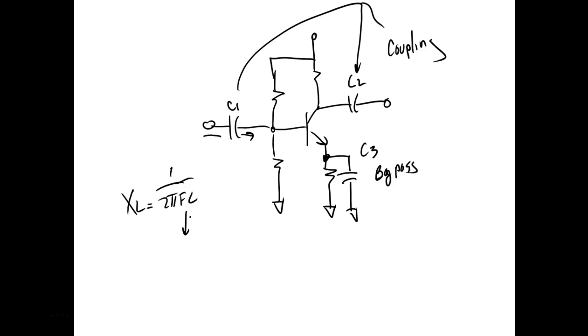Now what sets F2 is the transistor itself. So what happens is the frequency goes up and up. This guy here acts like a little old small capacitor, because of the barrier voltage. When we get up to a high enough frequency, it bypasses the base because it's so close together, and we lose control of the circuit.